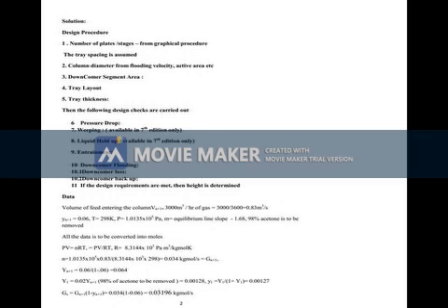Similarly, the liquid comes from the top. The liquid which moves from the first tray is called L1, L2, L3, like that, and finally it comes out from the bottom as Ln. The liquid entering is denoted by L0, and X0 is the concentration of the solute in the liquid. Usually the solvent will be pure, so X0 equals 0.